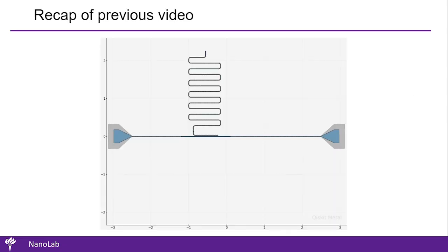In the last video, we designed a simple quantum chip resonator using Qiskit Metal library. As future designers, it's essential to evaluate your chip with powerful tools like HFSS. This simulation software allows you to extract key parameters, such as the coupling quality factor and resonance frequency, with high precision, which is critical information for guiding your fabrication goals. It also helps identify potential shortcomings or design mistakes early on, preventing costly errors down the line.